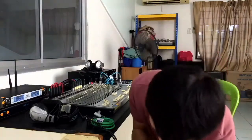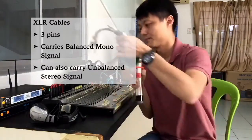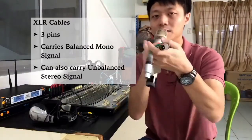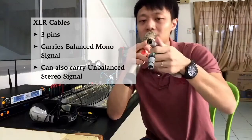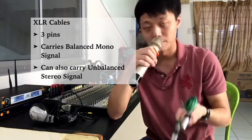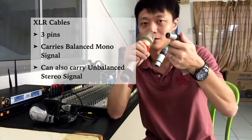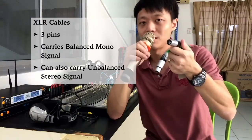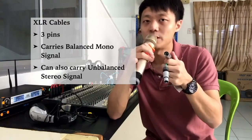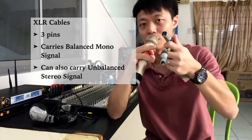Okay, the next cable that I want to talk to you about is called the XLR cable. This is an XLR cable. It has 3 pins. The 3 pins can be used to carry balanced signal, as compared to the RCA cable, which can only be used to carry unbalanced signal. When used to carry balanced signal, as I explained just now, one pin is used to carry the positively charged signal, another is the negatively charged signal, and the other is for the ground signal. So you have 3 pins.